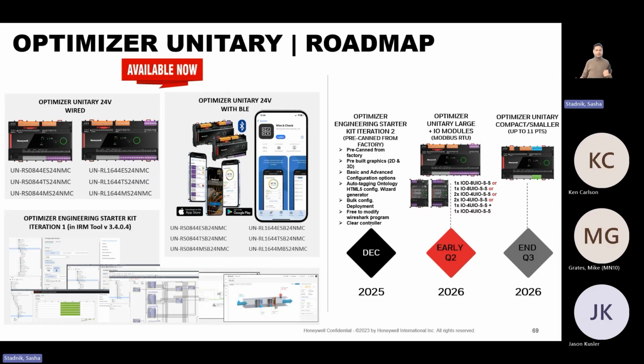ERVs, energy recovery ventilation units. So you have all those really complex, big, huge air handling units. It's not a plant controller, not a plant, but it requires more than 24 points of control. So what are you going to do, Honeywell? Because you had the Spyder Classic SR with Sylk IOs that it can do up to 45. So what is going to happen?